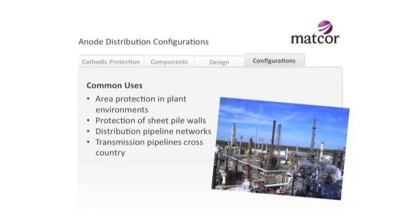Commonly used to protect plant environments where I have a real congested underground. Throw a bunch of deep anodes in, you throw a ton of light up, a ton of current up, from these deep anodes up to the surface, and try to protect everything, try to light up everything.